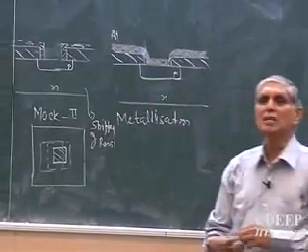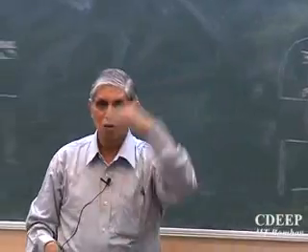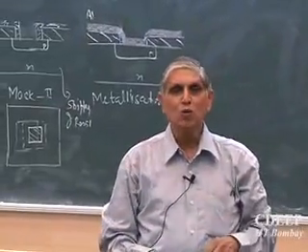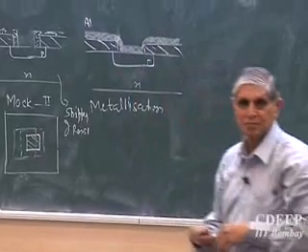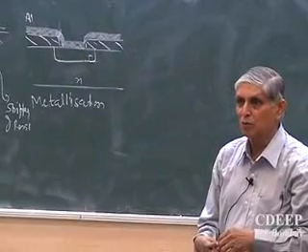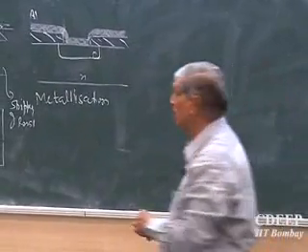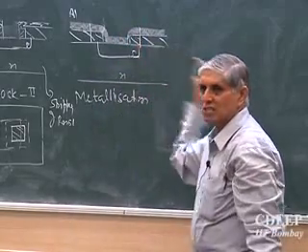But aluminium will get deposited on every place, on all layers. But I need contact only in this region. So what should I do? I must etch aluminium from the rest of the portion, except where I need only this much. That is, it covers the window.